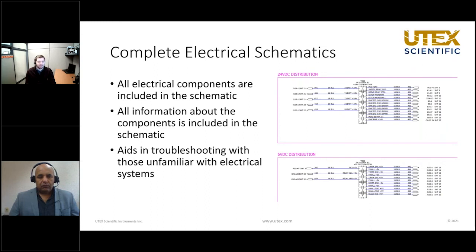Furthermore, many of the people running these systems don't necessarily have a lot of electrical experience. So once we walk them through how to safe the system, we can direct them to the exact location of where we expect to see the issue. Did something happen recently with the system? Was it moved? Did a component get damaged or did a wire get tugged loose? We can tell the clients exactly where to look so they don't waste any time hunting. You've got to check terminal block 53, block 1, position 2, which should have a blue wire that is numbered 302.